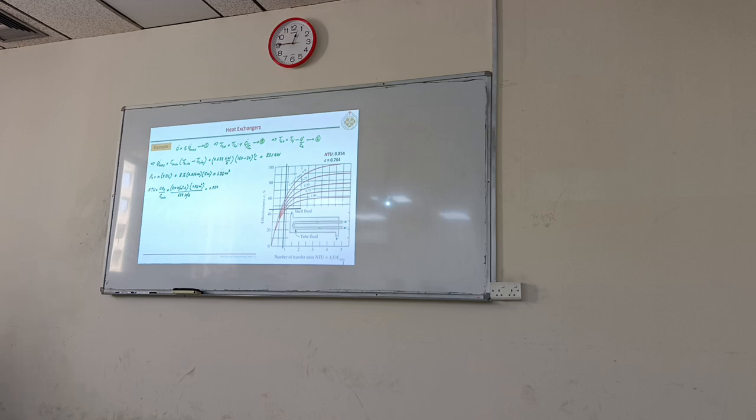Okay, 46 or 47. Let's see what is in the book. 47, 0.47. So find out Q. This is Q maximum. So actual Q is only 39. Maximum possible is 83.1. So TCO and THO. To increase this, increase the area or increase the U, right? Increase the area or increase the U.